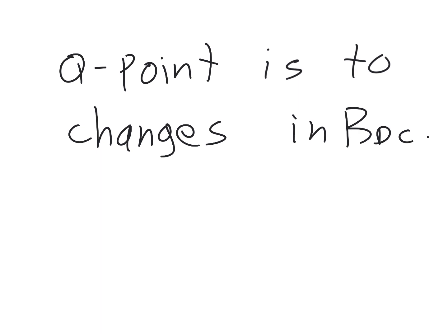So that method is totally suitable to use in a switching application, where you basically want to either cut off or saturate the transistor, or oftentimes in the active area, but the beta is not such a big deal because you can design around it.